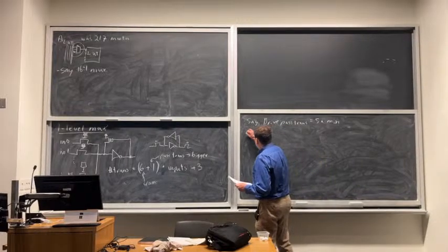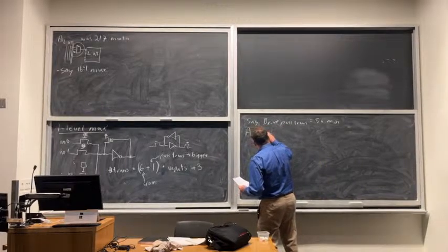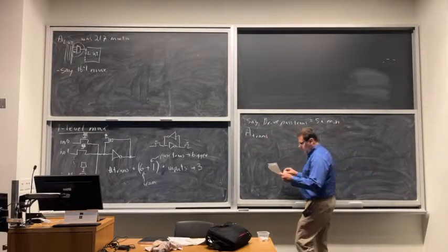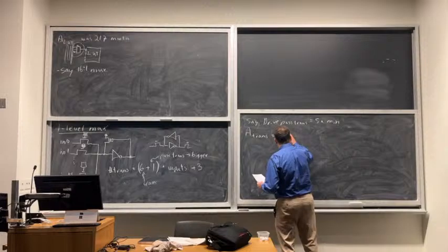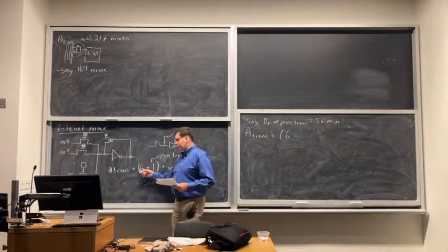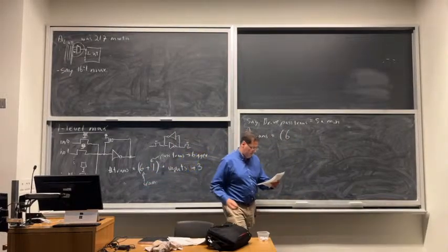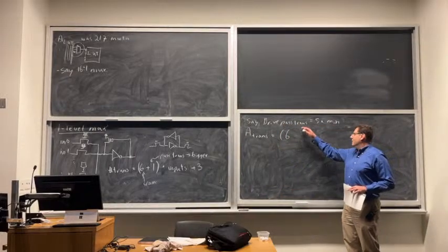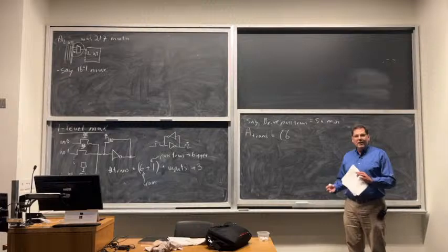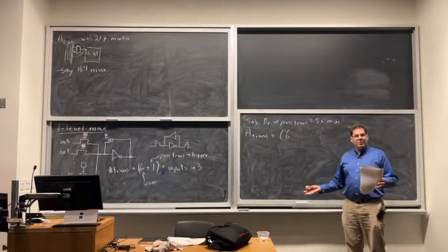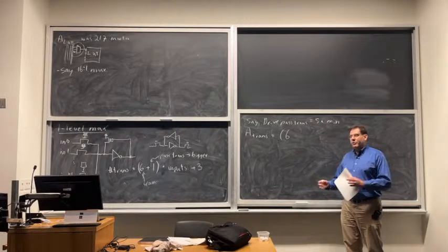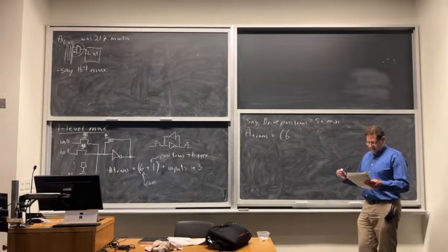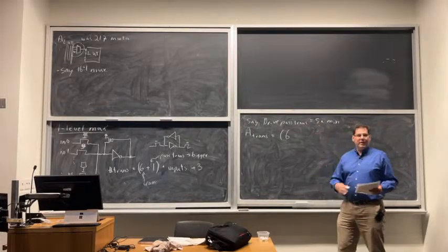Okay, so with all those assumptions, I can now compute my area of all of these transistors. And it's just equal to the 6 SRAM transistors, which are small. So I'm going to count them all as a minimum size transistor. And then we had this fairly simple equation. As we make the drive strength bigger of a transistor, its width or its number of fins gets bigger, but we don't have to increase the spacing around it, so the total area doesn't go up linearly. Well, if I need to make it 5 times more drive strength, I don't need 5 times the area.